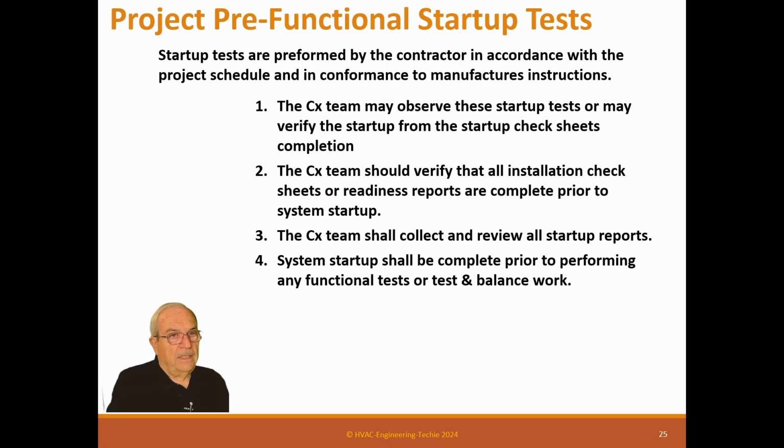System startup should be complete prior to performing any functional tests or test and balance work. And I can't tell you how many times we've done test and balance jobs where not only was it not started up, it wasn't complete. So if you actually did your job and everything was started up before the TAB guy got there, he'd be beside himself because he's going to make more money because he doesn't have to have as many trips to try to figure out when you're ready for him.